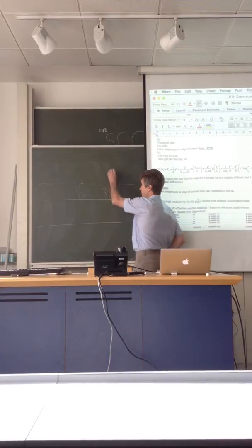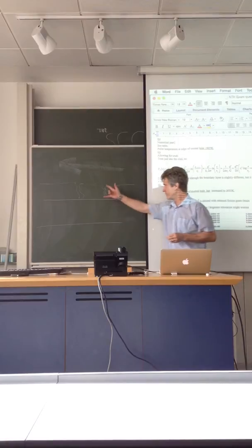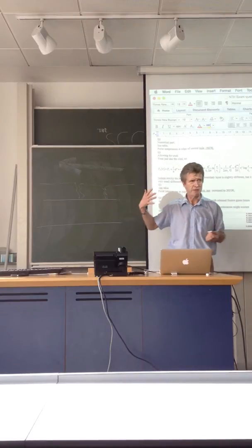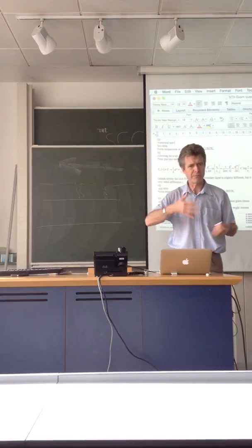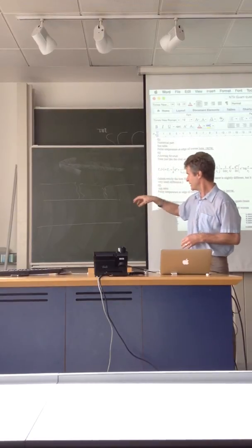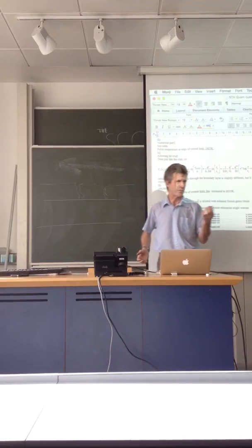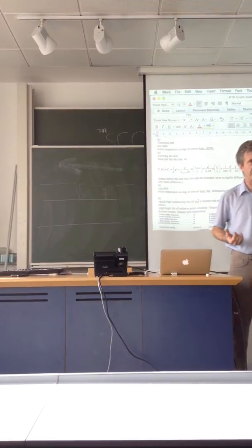So the picture we should have is water flowing past a thin layer of crud, 50 micron or so, like half a millimetre. It varies from a tenth to a millimetre. It has lots of these tiny holes that go down to the bottom. And the crud is porous, a bit like kettle scale or chalk.